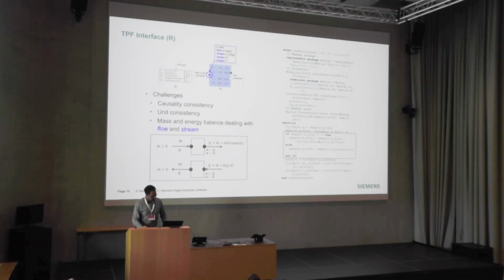To manage that, we had to think about two use cases. First, when the mass flow rate comes from Modelica and goes to the Simcenter Amesim world. For that, we use the inStream function to be sure that the enthalpy we send to Amesim is the one coming from Modelica, so the one coming inside the interface.